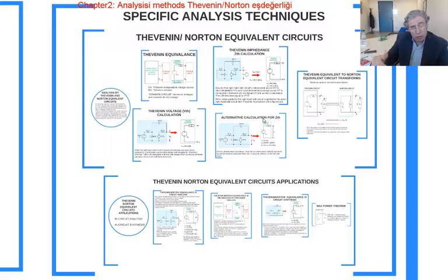You're going to buy a resistor whose power limit is, let's say, 0.5 watts. So according to that limit, you can change your buying policy, or make the decision about which resistor you're going to buy. That's why we are calculating all the elements' currents and voltages.